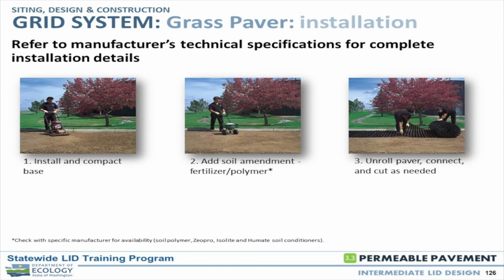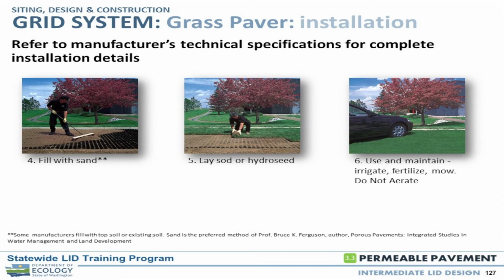So again, it's going to be a similar sequence of construction, you can imagine, where we're putting down our base. If we need to add some sort of fertilizer, proceed with caution on that. But anyway, we put that down and then we unroll or place our pavers and then backfill with our sandy loam and then generally seed it. That's how it works. And then, of course, obviously, we use it.